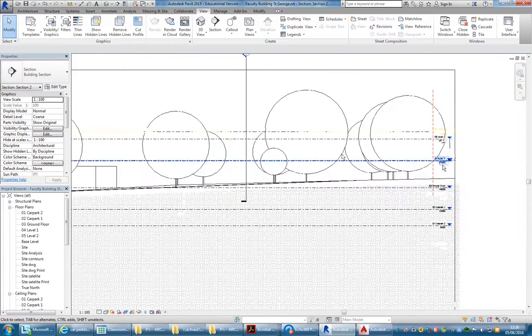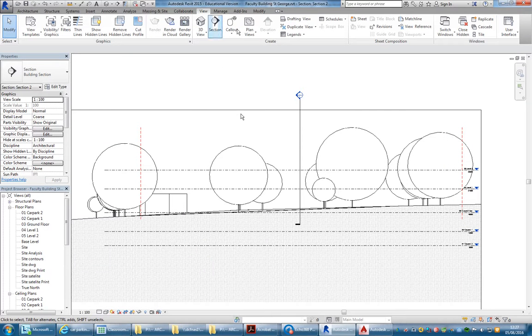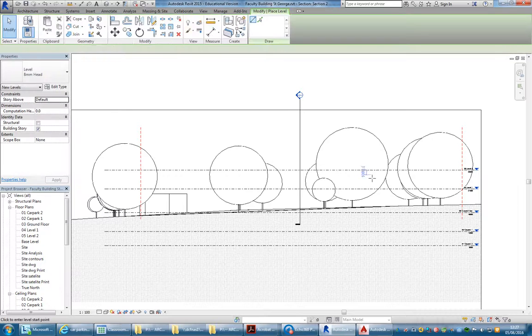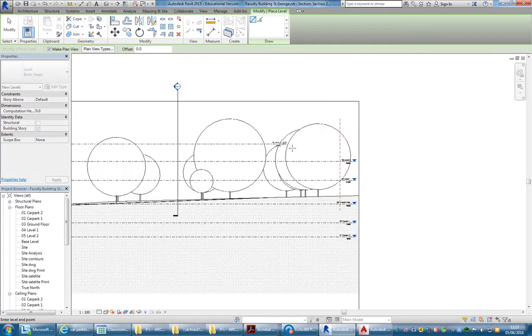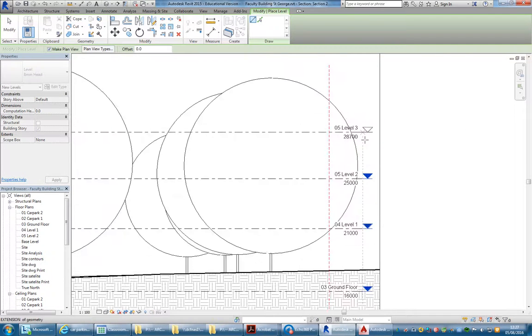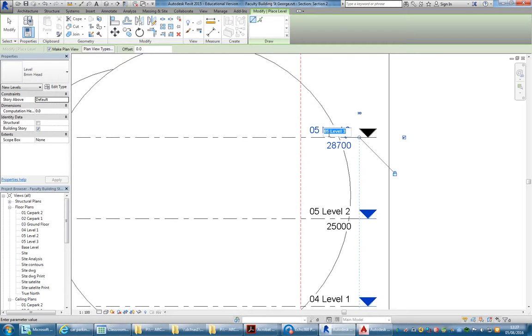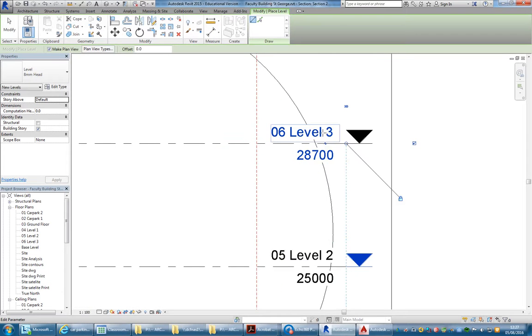So you need at least 2 levels above the ground floor. And then you should always have a level for the roof in addition. So the basic rule of thumb is at least a level for each main floor, and then a level for the roof. If you want levels for other things, just to indicate height, add them in afterwards. So ceilings, parapets, things like that.